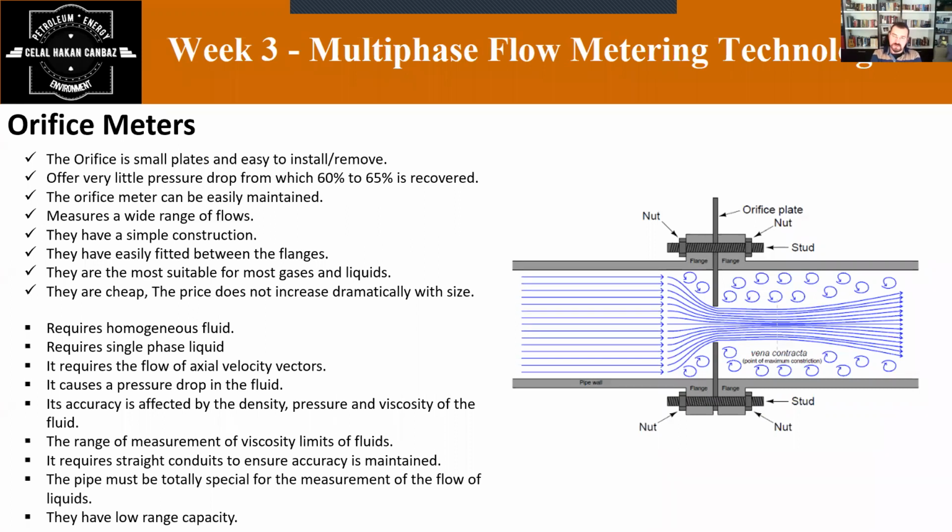We are using this for gas measurements through a pipeline. The flow rate is calculated from the pressure differential created by the fluid passing through an orifice of a particular size, of course, and other parameters such as static pressure, temperature, density of the fluid, and of course the size of the pipe.